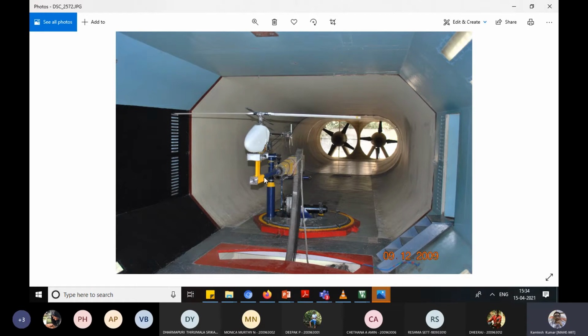So that is called angle of attack there. And the other thing they can do is the yaw also. So mostly they are looking at the side slip as well as the yaw angle. So they can change here. Not just angle of attack, but side slip also you can get. Yaw angle at least you will get. Roll facility is not there. If you want roll, then you should have another setup here which rotates. It means you can rotate your models.